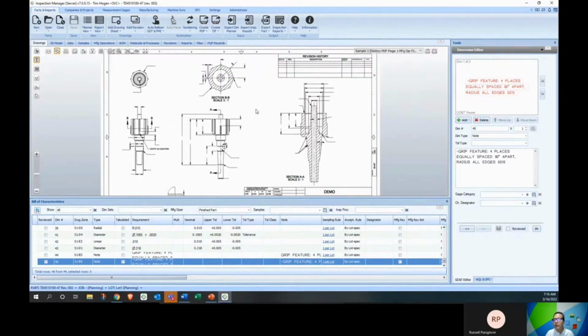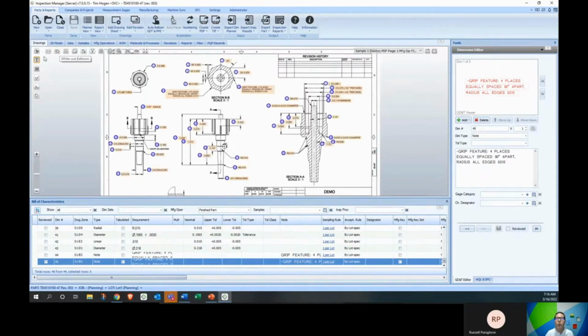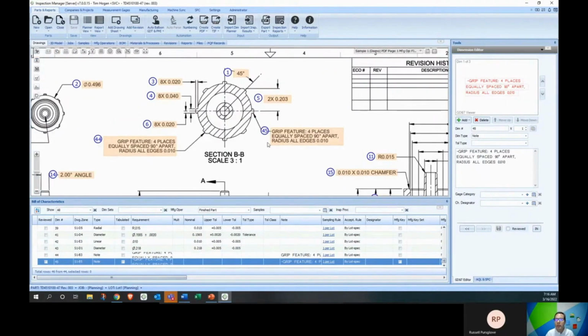And if we click off of that, we can see everything is done, and we can turn off our whiteout and see all of our dimensions. Now we can also see that they're significantly out of place, right? Because we always put it on the end, what we call n plus 1. So it's the end spot and then the next feature past that. So that's where these lined up, because we don't always know if it's a revision, engineering change, or something along those lines to where it needs to be kept separately and added to the end, or if we want to include it. In this case, we just want to include it.